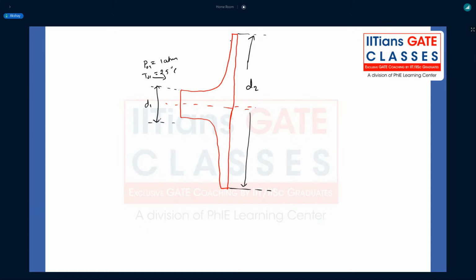So now what they have given, this compressor has a pressure ratio of 5, and we can use the properties of air, gamma 1.4 and Cp as 1004 joules per kg Kelvin. And they have also given the polytropic efficiency of this compressor is going to be 0.8, right?